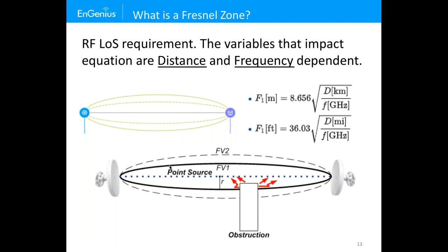So when it says minimum antenna height, it means the minimum height has to be above any obstacle for it to be unobstructed. Now, it could be obstructed. Rule of thumb is 30 to 40%, depending upon whatever you're doing on the network. I like to plan for 100%, and then from there you have reality. You can start seeing how much you could get with the obstruction itself. But if you could get 100% unobstructed in the real world, then I would say go for that as much as you can.